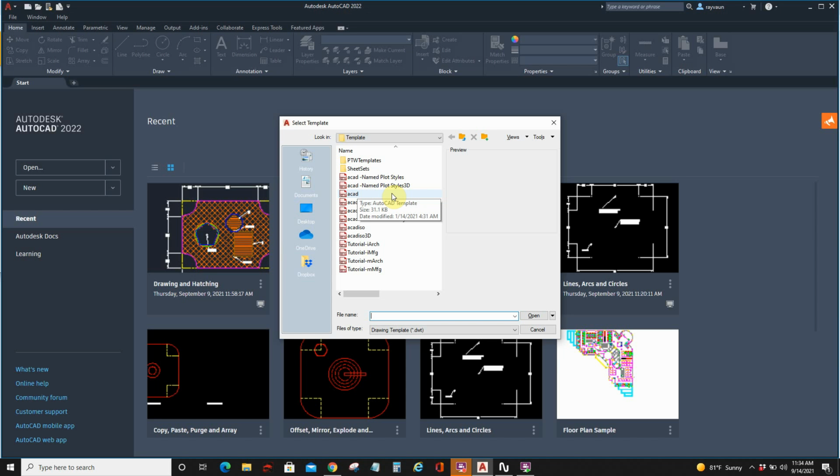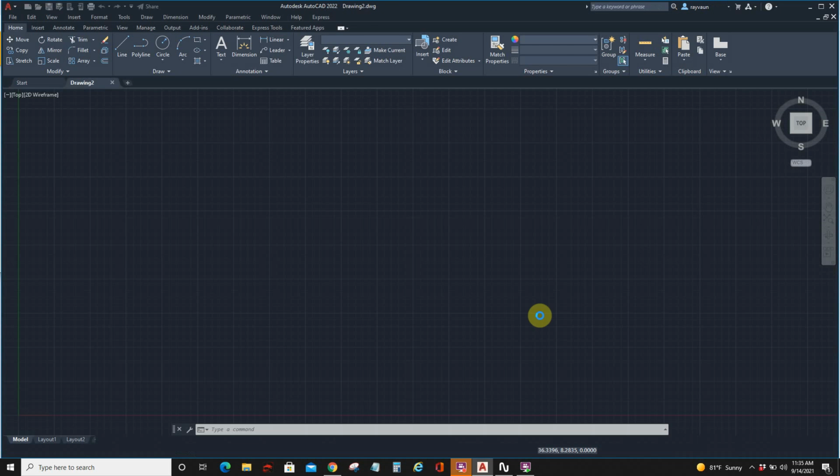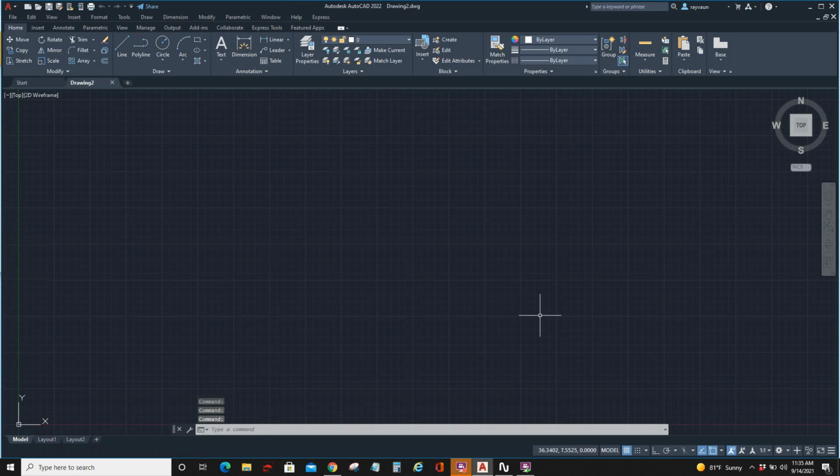There are different file types. We have the DWG, which is a drawing file. We have DWT, which is a drawing template file. We have BAK, which are backup files, and plot files, PLTs, but we don't use them a whole lot anymore since nowadays we go straight to our printers. So for the English templates, we would start with the ACAD .dwt right here, and you get basically a blank screen, but it's set up so it works well to put English units in it.